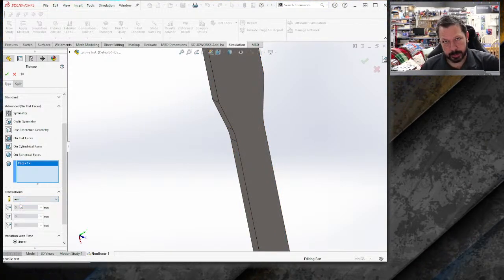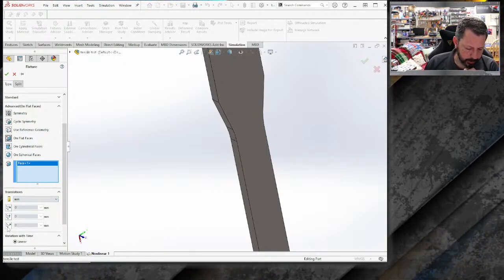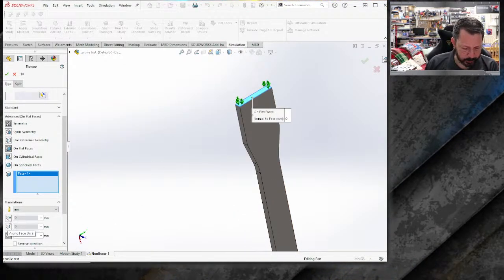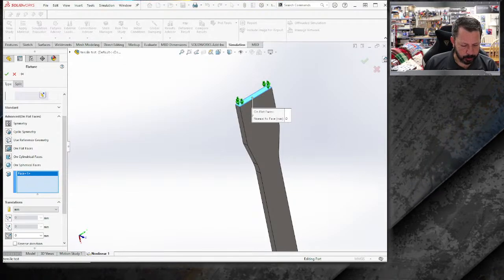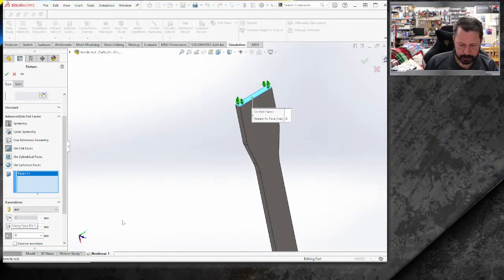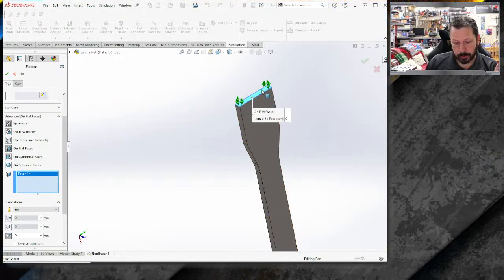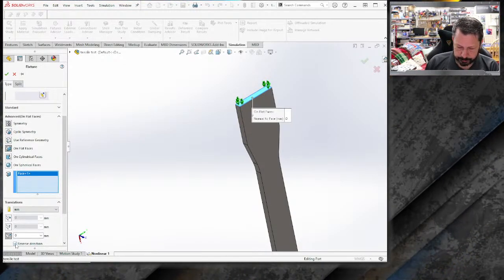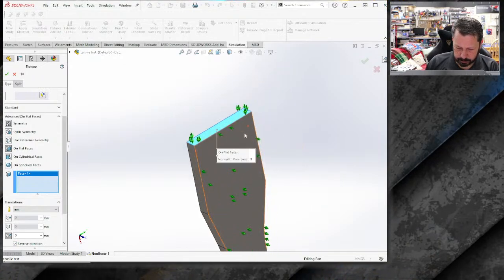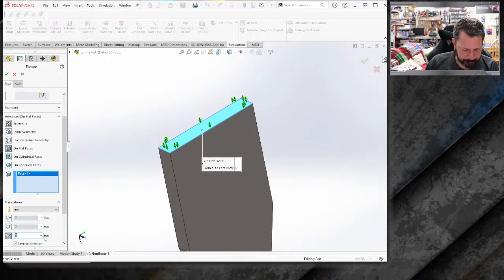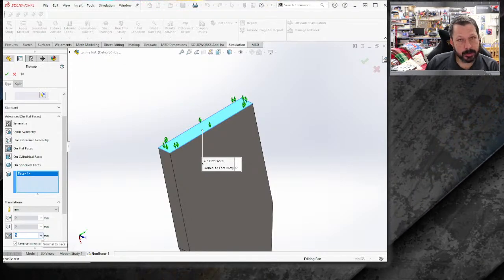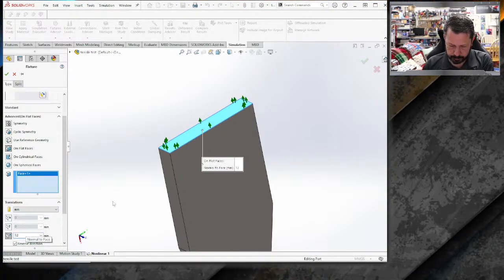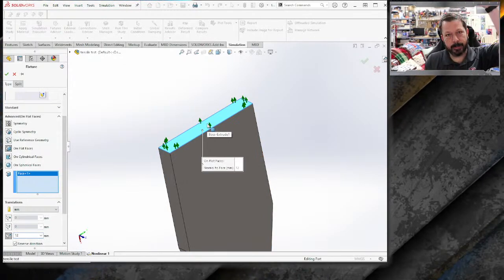And we'll leave it in millimeters. We built everything else in millimeters. Now these are different directions, so they may not always make sense on which one is which: normal to face, along face direction 2, along face direction 1. We want our translation to happen normal to the face that we selected. So right now it's compressing it, so we do need to reverse that. And let's do 12 millimeters. That's probably plenty enough. So now that face is moving up by 12 millimeters.